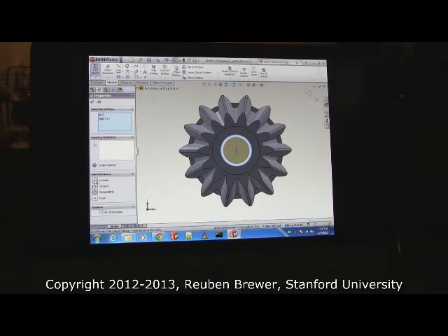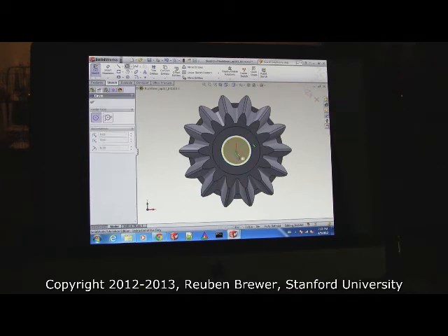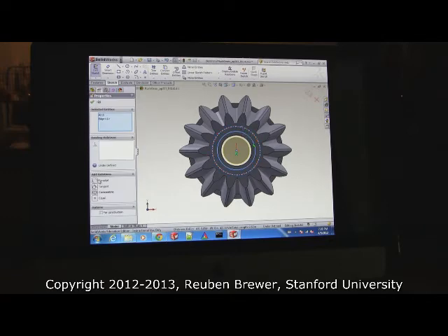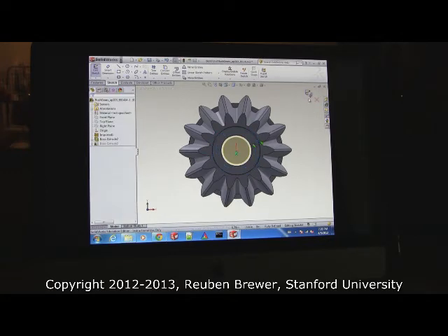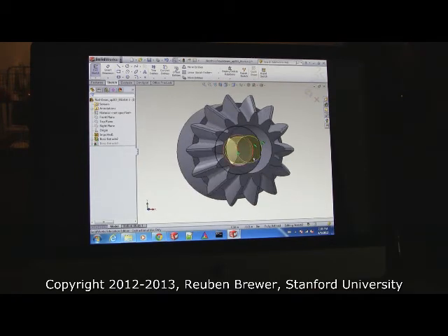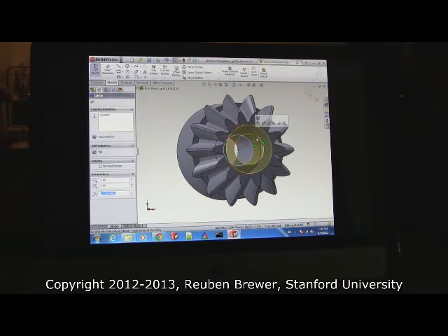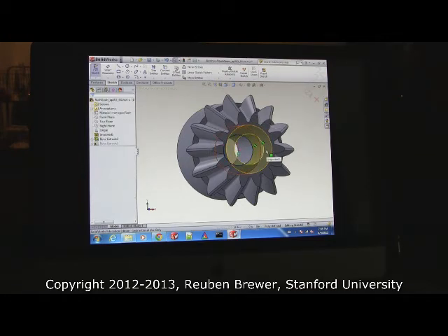The goal is we're going to do this twice. So now we take another circle. We select that and this. Hit co-radial. Exit your sketch. Before I press the button, everybody's got to have it look like this. We've got two circles. Basically, we're trying to extrude an annulus or a ring here. See how I have this circle on the inner and that circle there? Is everybody here?